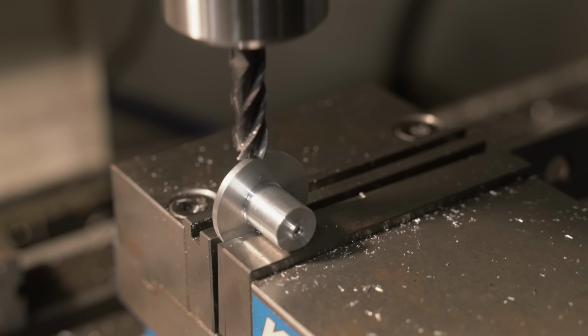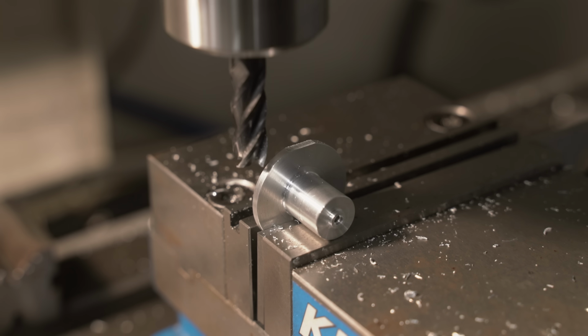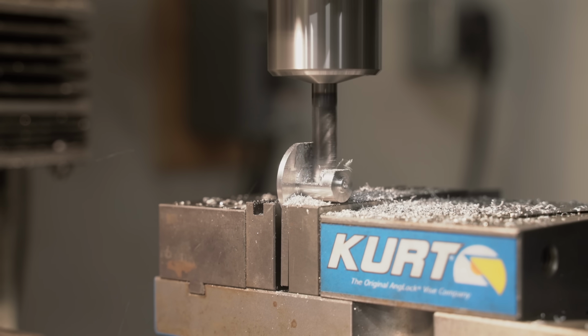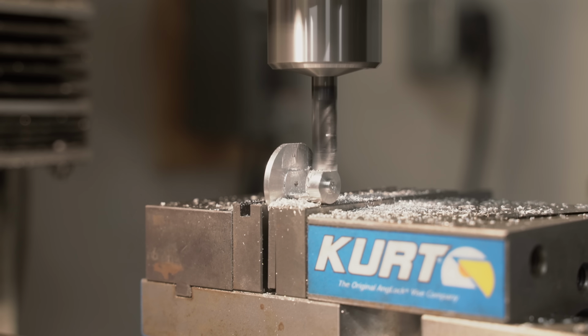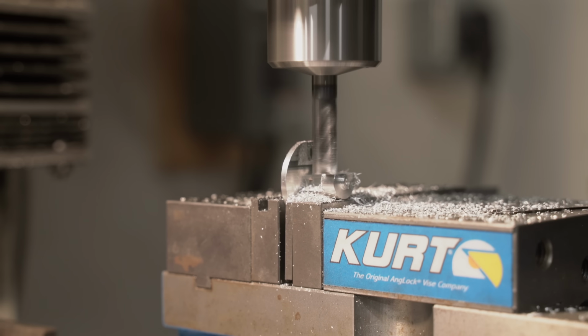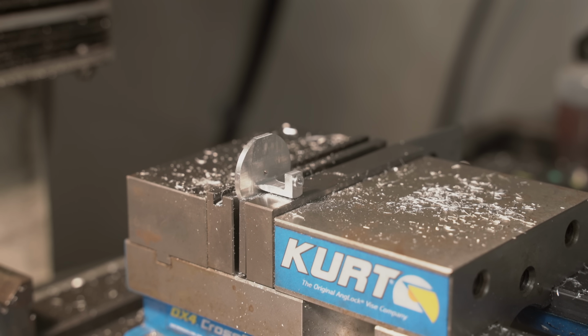Again, the first thing I do is machine a flat spot so that later, when this part goes back in the vise, I can guarantee it's facing in the proper direction. Then I mill a slot into the sample holder. This is where the movable mirror will be mounted. After that, I trim the excess from the edges. Looking good so far.